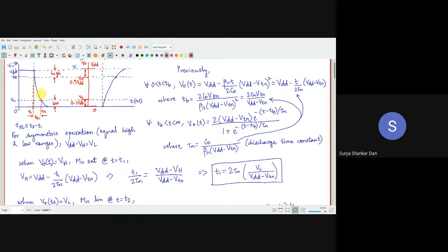Now, interestingly, in certain applications you might be even more rigorous, where the logic should be very reliable. In that case, instead of 10%, I can say that for my particular application, for my own particular IC, where we cannot afford any errors, I will put VH and VL at 5% of VDD.